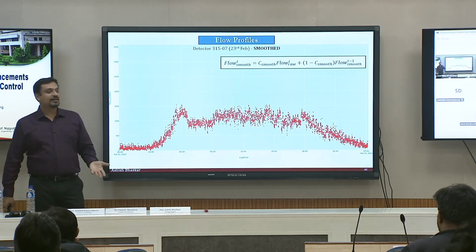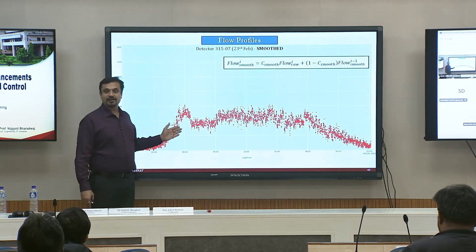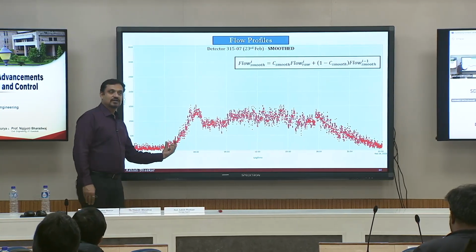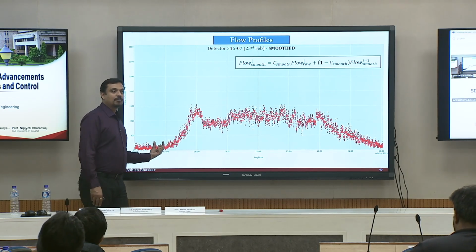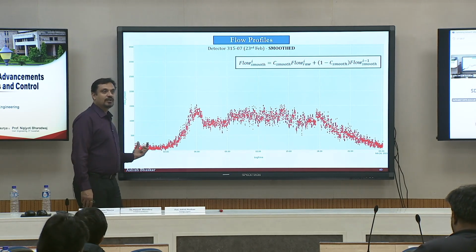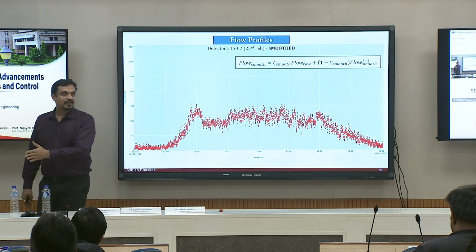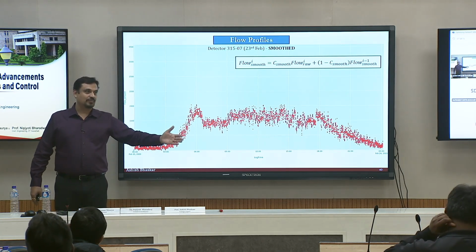So what we recommend is to get your exponential smoothing done. You have 3 20-second values, aggregate the last 3 to get a 1-minute one, and then do an exponential smoothing on it, so that you have data points every 20 seconds, but they are smoothed over the last couple of times.